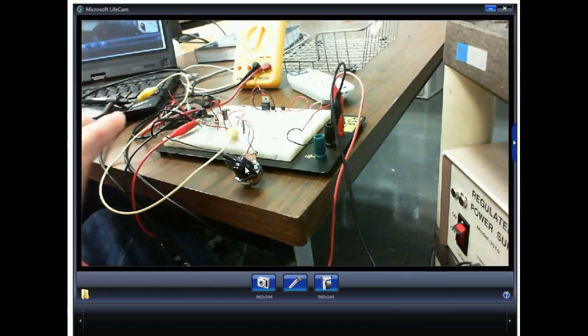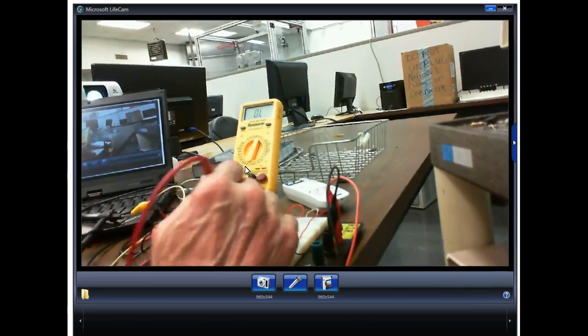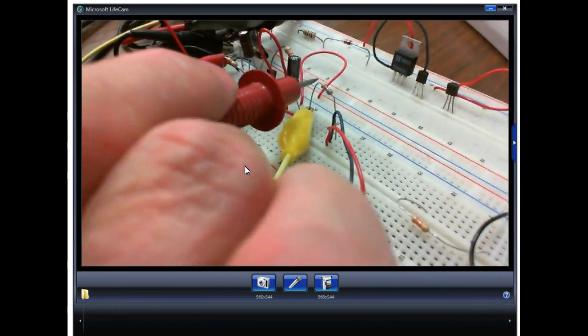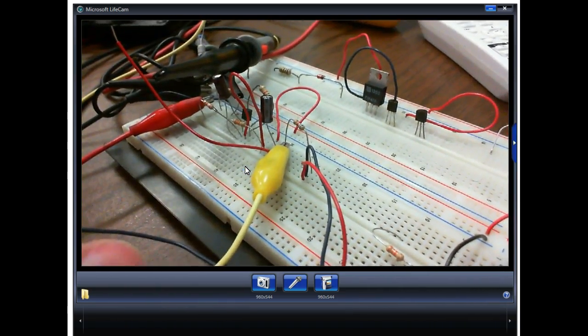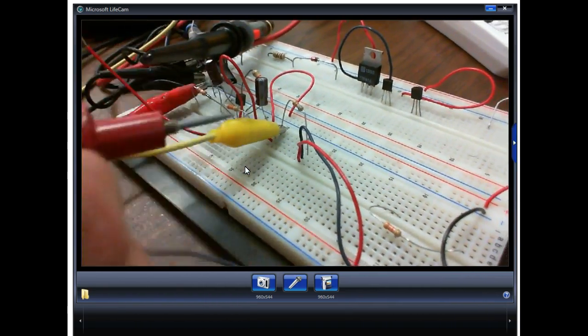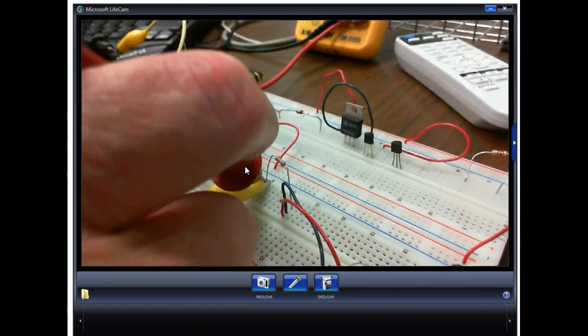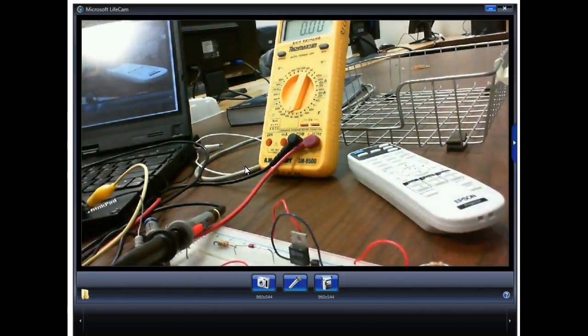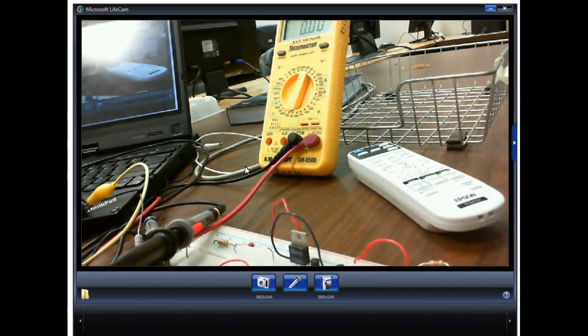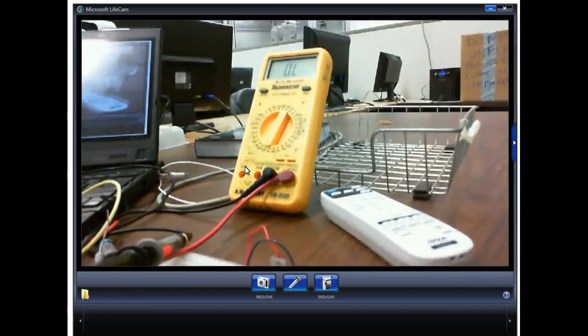It's okay now. It was measuring about 15K when I touched the 2 leads together. Here's 6.8K, here's my pot, here's my other side. What was happening is it measured over 30K, and when I touched it over to my other side, it wasn't going to 0. So if you've got a dial meter and it's doing something strange, you need to check it. So now it looks okay.